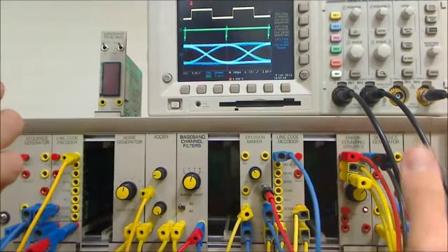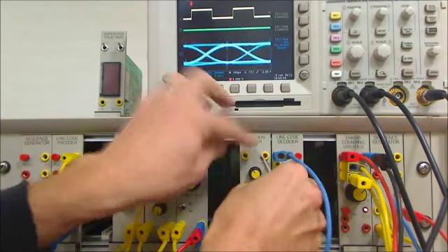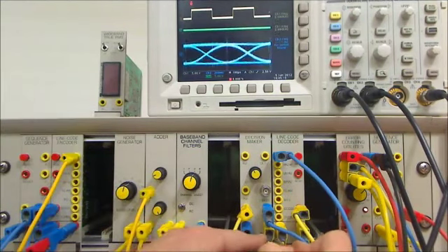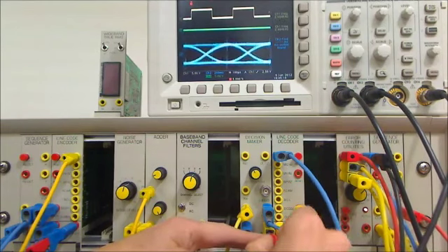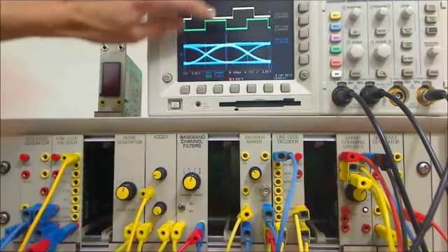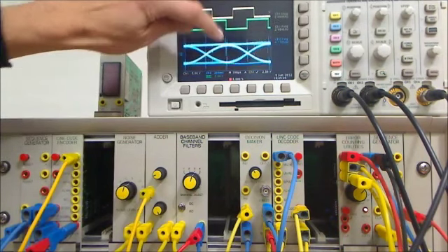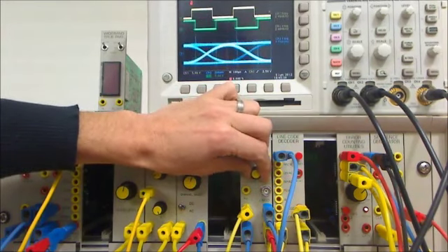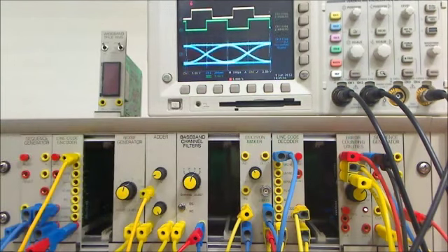If you don't happen to have another channel on your scope, another option is to consult the user manual, and you'll find that the output bit clock from the decision maker is such that the decision point is at the negative edge of the output of this bit clock. So you can see this is convenient. Viewing the negative edge of that bit clock will also tell you where the decision point is.